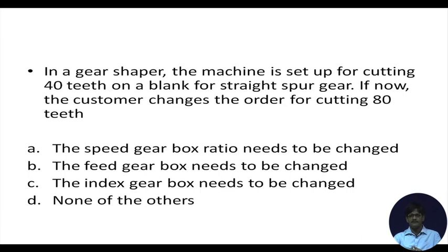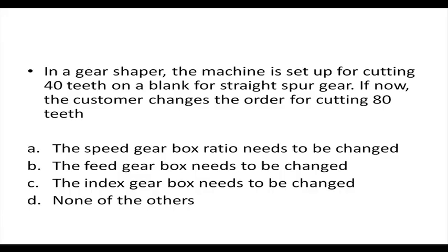Second one, the feed gearbox needs to be changed. Am I changing the feed? Do I need to change the feed? Not really. Feed is going to define the surface finish, and the customer has not stated that he wants to change the surface finish. So, we still have no need to change the feed gearbox.